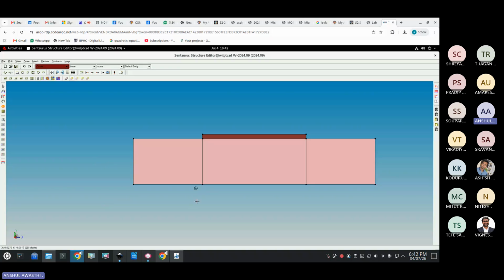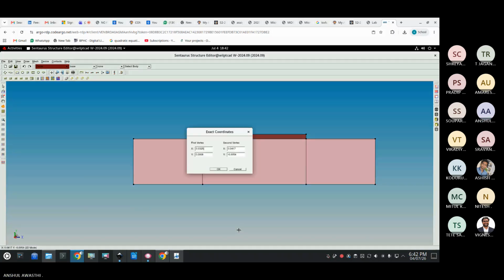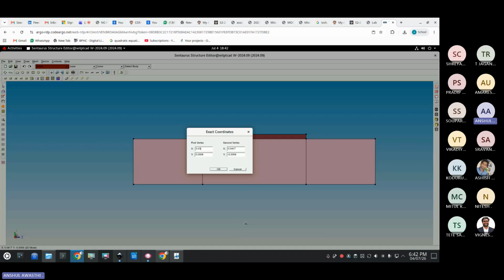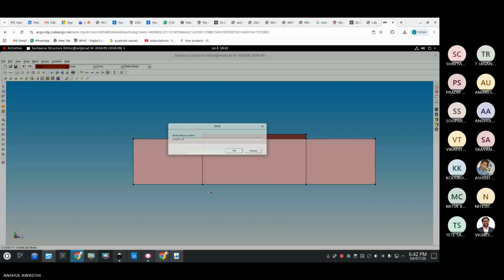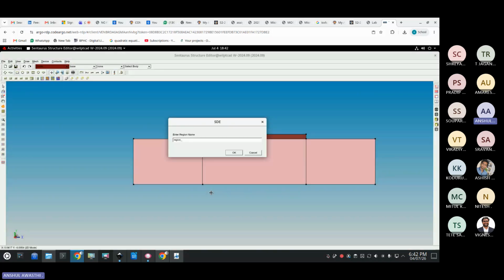So I'll just make a rectangle. In the X direction, it will be from 0.030 to 0.075. In the Y direction, it will be from -0.002 to 0.00, since it is downside of the wire. Okay. I'll give it the name O2, oxide.